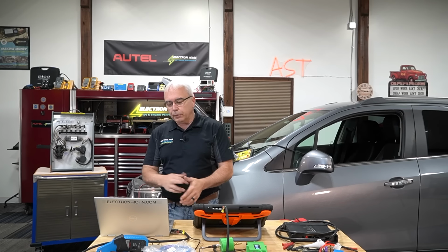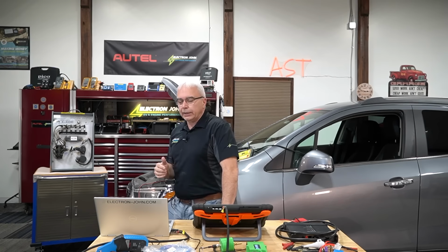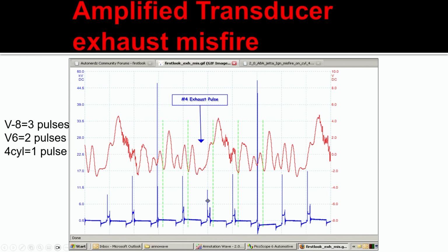And then he's also got a little tool here, another little adapter that's made to test ignition systems, or basically things with magnetic fields that are collapsing, right? So most of the time you're going to be using it to test ignition coils and stuff. So I'm going to be using some of these things just as quick go-to tests as we go through there. So focusing our attention back on the PowerPoint before we get started on the car, some of the stuff I'm going to be looking for.